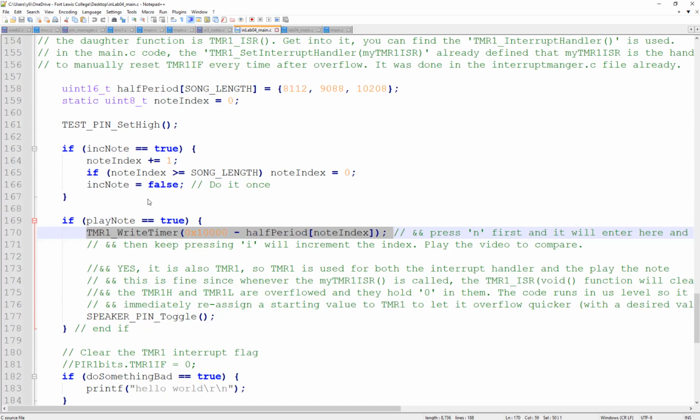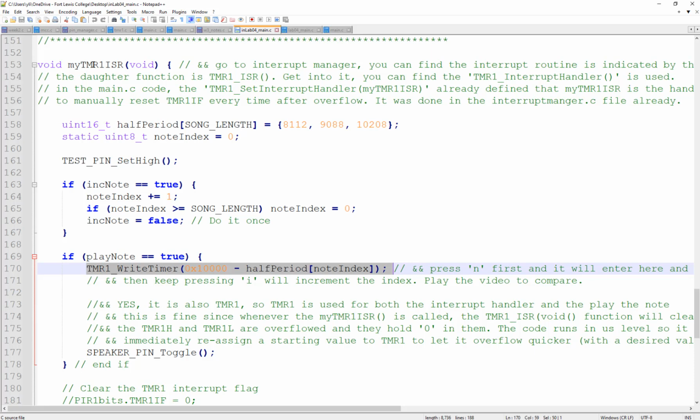So now you get confused. Timer 1 interrupts, assuming that at the very beginning timer 1 has 0 inside. After how long is it going to trigger, so that the flag will be 1? Remember from lab 3? 2 to 16. But what's the value? Remember we used 4.1 milliseconds, right? So after 4.1 milliseconds, it jumps to here. So what's the flag? The flag becomes 1, but whenever you get into this one, it will clear it. You get a 0 for that flag.